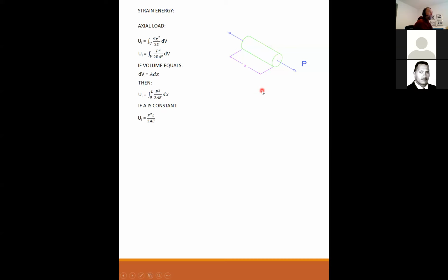So there's no moments, there's no shears. All you have is simply supported axially loaded members that are either in compression or tension. So for a truss, you can add up the internal energy and solve for a deflection at any given point based on this principle of energy. So kind of tuck this away. This is used mainly for the analysis of trusses.